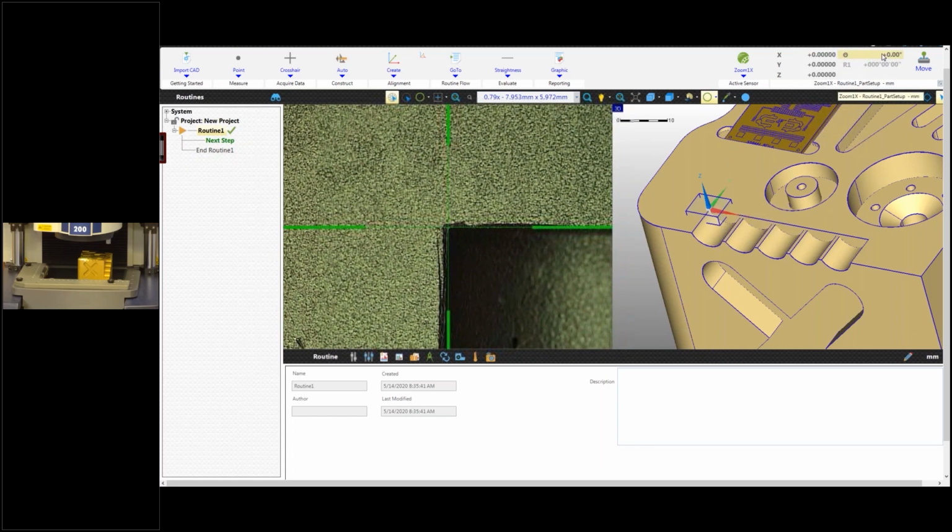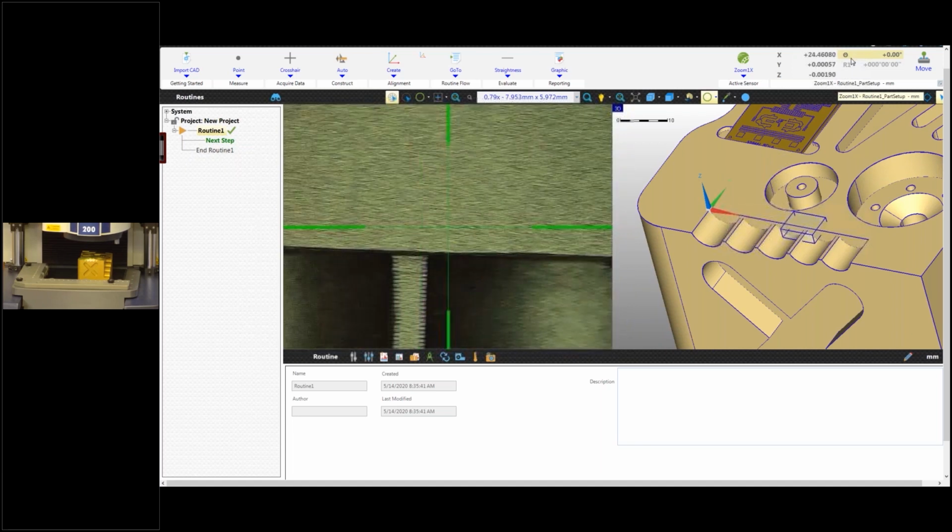This would be your angle button in MeasureX, or it would be the little angle graphic in MeasureMind, but it'd be the fourth button in your DRO at any rate. And it's our fourth button up here. It's got the Greek theta symbol right there. So if I ever say theta, that's what I'm talking about. And all this is going to do is set our x-axis rotation.